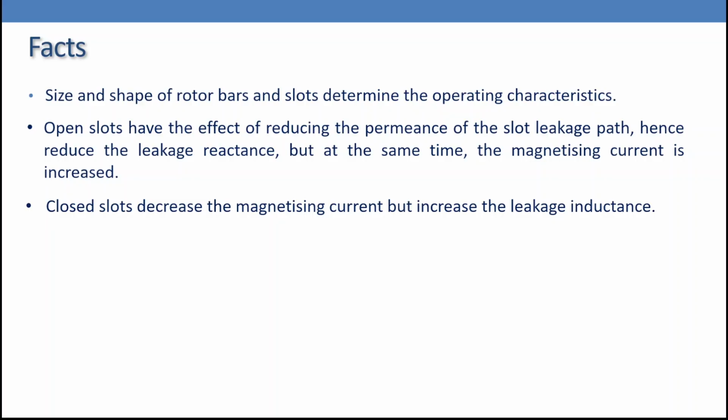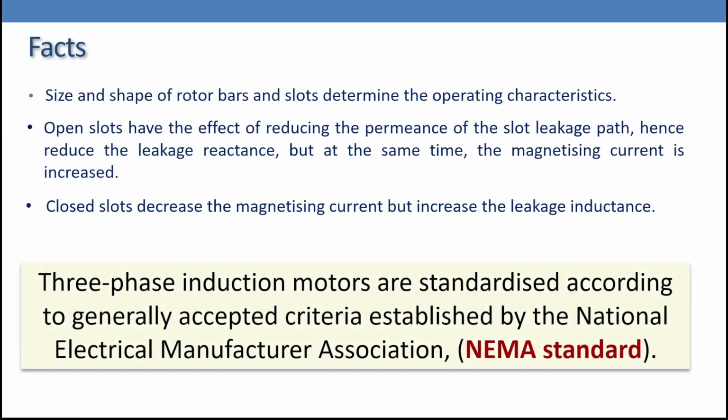And if you remember from the previous chapters, if the rotor resistance, for example, is increased, the torque characteristics will be different from the normal rotor resistance. Accordingly, three-phase induction motors are standardized according to generally accepted criteria. This criteria is established by the National Electrical Manufacturers Association, the NEMA standard. And this is why we have different motor classes, and each class is suitable for specific applications.